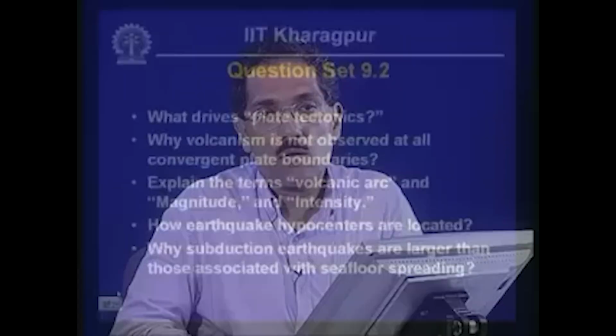And if you recall the discussion that we had some time back on rock strength, the strength of geologic material usually increases as the compression increases at a particular location. So you would imagine that in case of thrust faulting, where compression is the major principal stress, you are going to have a larger strength of rock mobilized before the failure takes place. Because the strength is higher since the rock mass is in compression, it is going to be able to mobilize a larger magnitude of strength before failing.